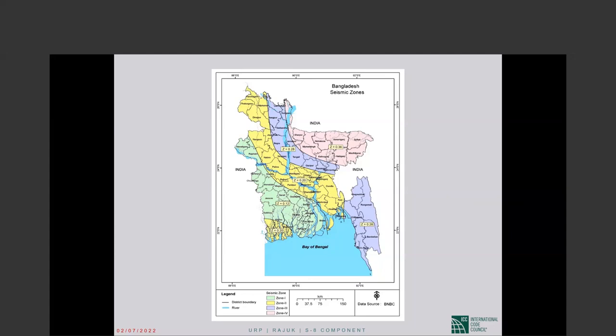Any detailing from collector to shear wall? The detailing requirements for collector to shear wall. If it's just a general question, are you going to go over that detailing? I don't know that there is any specific detailing requirement for collectors. We have to have the reinforcement that is needed, and then the overstrength factor on the connection. But there is no special detailing requirement that I'm aware of.